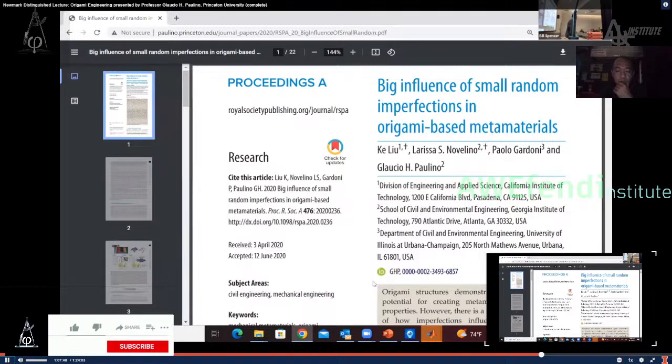So if I take that Poisson ratio, which has a length scale at the microstructure level, and plug it into momentum balance equations, where sigma now has a Poisson ratio that is actually a Poisson ratio for the metamaterial, do you think that will give us results as we expect from continuum gradients? Continuum gradients may not have those points where they flip over from positive to negative. When you plug it into momentum balance equations, what kind of issues can you see?